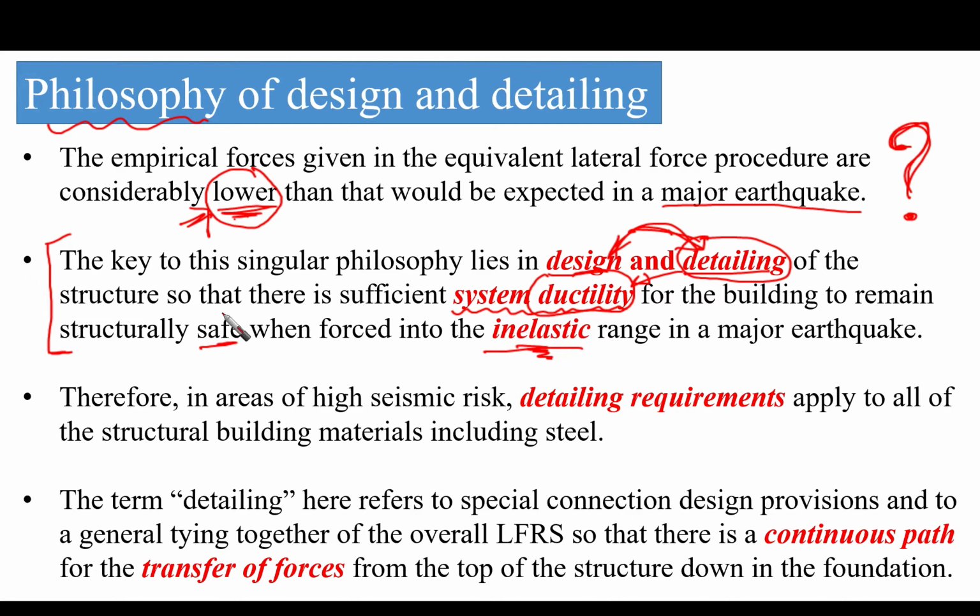This detailing and the design as well are going to keep our structure safe during the inelastic range. That's the philosophy that we have. This is why we said that ASCE is not all about loads. It is also about detailing and configurations. Therefore, in areas of high seismic risk, detailing requirements apply to all of the structure's building materials, including steel.